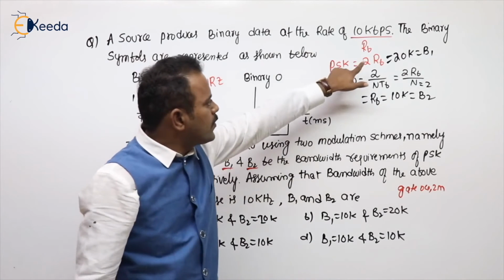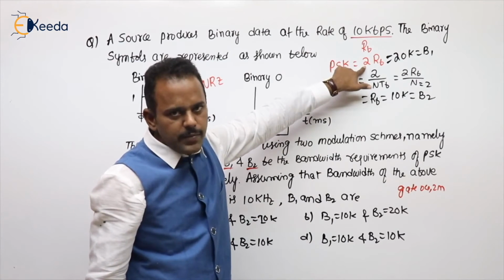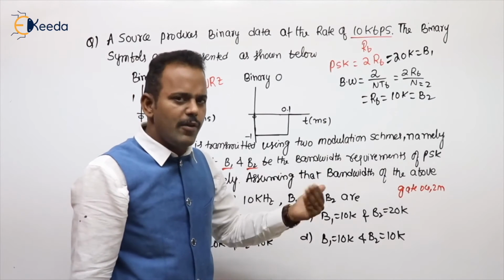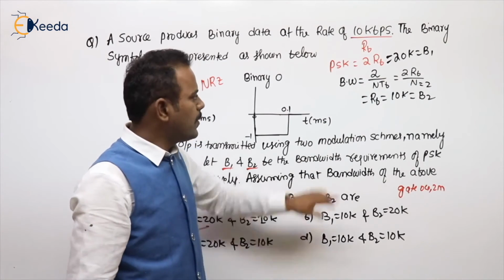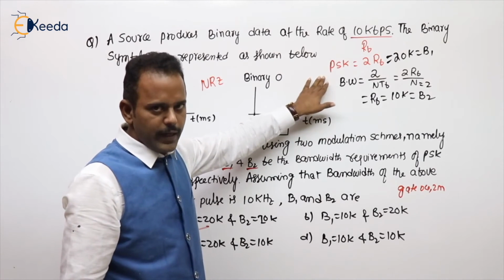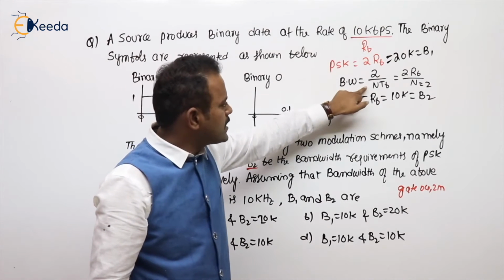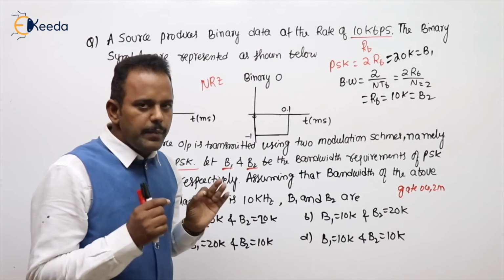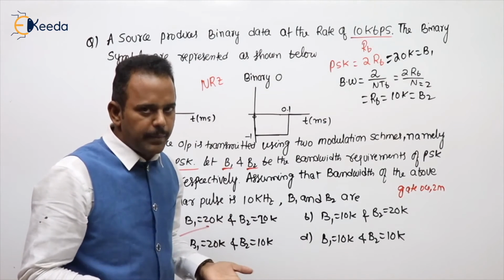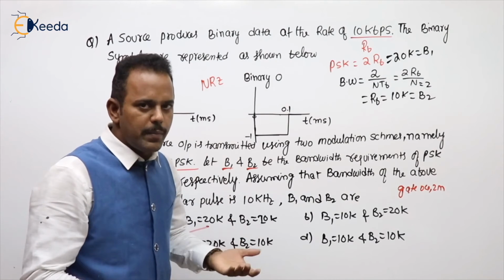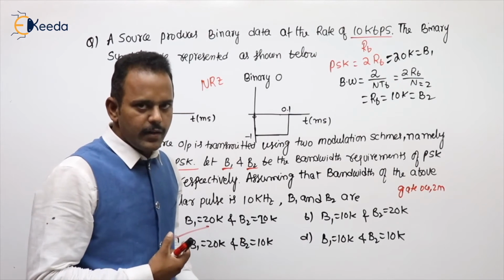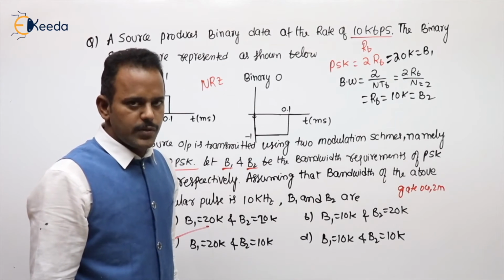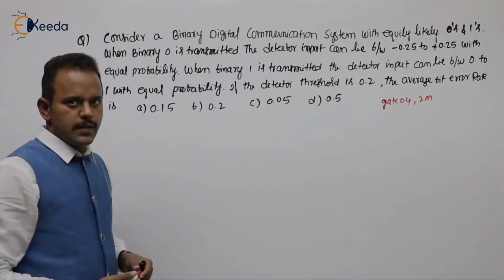This is the bandwidth formula for PSK schemes, and this is for any modulation schemes, MPSK schemes, even for the binary also. But I gave binary at the start, so I am writing it separately. So for binary PSK, N value is 1, so it becomes 2RB. N means number of bits transmitting at a time. M means maximum possible number of symbols. See our class on the MPSK signaling schemes also. Clear? See the next problem.